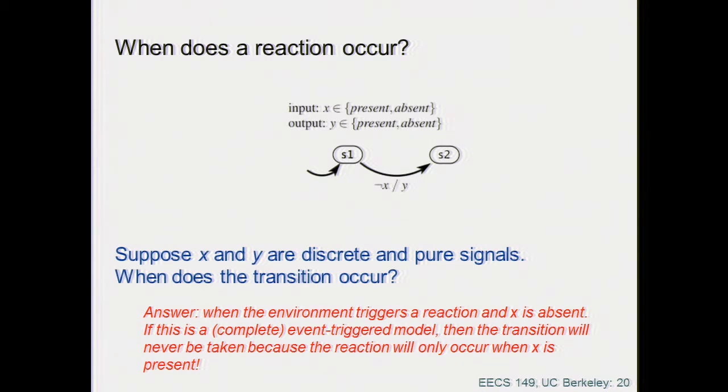Ping! Aha! Okay? So every time you do a ping, the circuit works and power is consumed to do absolutely nothing, right? And so when you study what the cycle is, you have to balance the fact that you want to be able to catch signals when they come in, and at the same time you don't want to wake your system up too often.